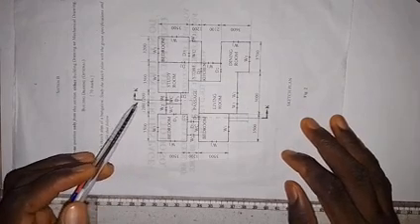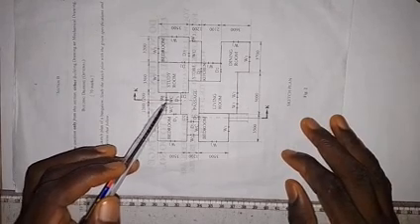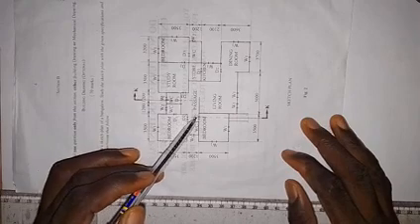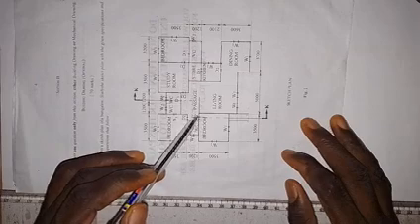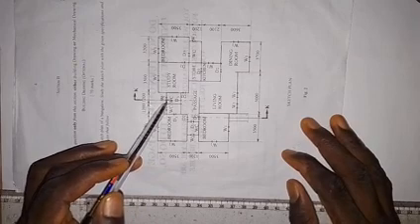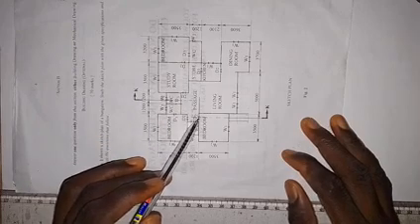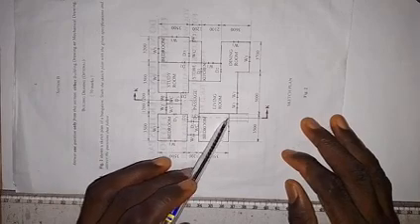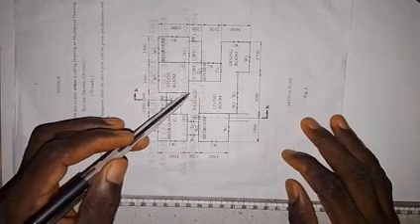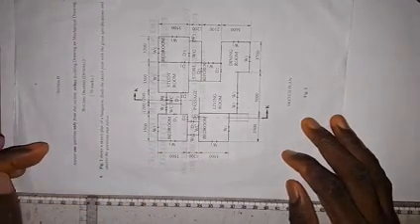One thing that we need to take note of is the number of walls that the cutting plane touches. The cutting plane touched this wall, and it touched this wall, that is the second wall. Then this wall here, it cut this wall, and within this wall we have a door, and within this wall here we have a window, and within this wall we also have a door. Then coming here we have a door within this wall, and it also cut this wall here. But here we are going to see the edge of this wall, and we also see the edge of this wall here. So those are things that we need to take note of.